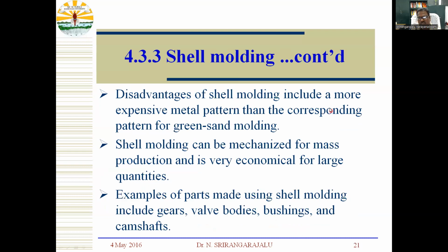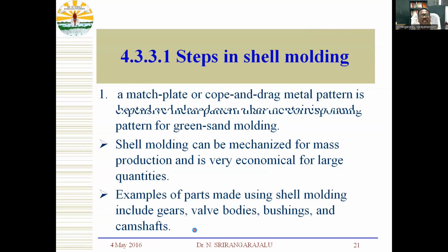Disadvantages of shell molding include a more expensive metal pattern than the corresponding pattern for green sand molding. Shell molding can be mechanized for mass production and is very economical for large quantities. Examples of parts made using shell molding include gears, valve bodies, bushings, camshafts, etc.